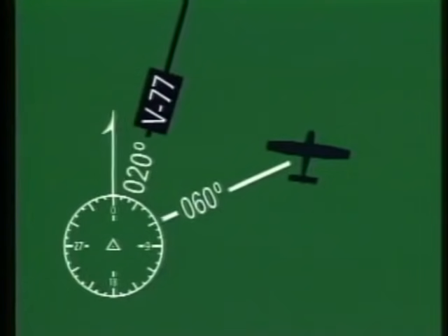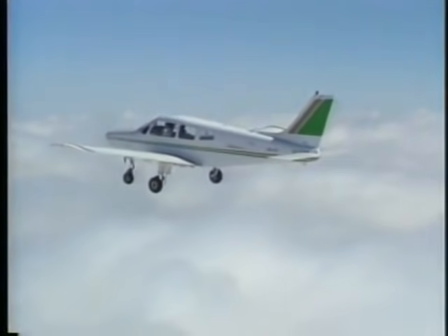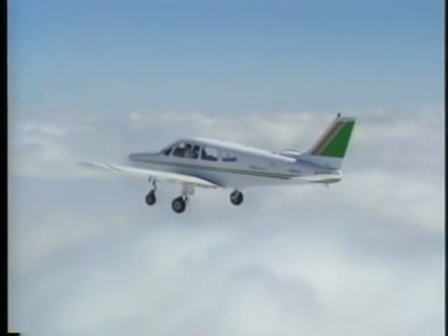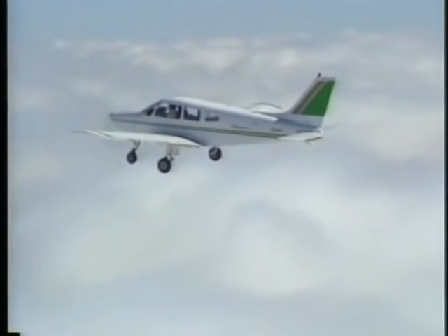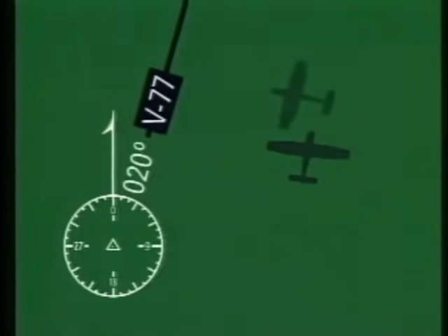Now that you know what radial you're on, you need to choose a heading that will enable you to intercept the 020-degree radial. The angle of interception depends on several factors, such as your ground speed and proximity to the radial and navigational aid. A wide range of angles may be suitable. One possibility is to fly a 90-degree intercept to the 020-degree radial. In this case, you need to anticipate your turn onto the airway, since a 90-degree standard rate turn takes 30 seconds.